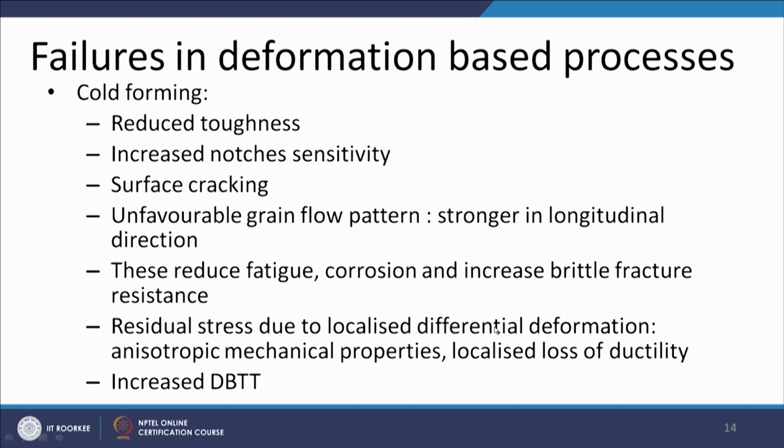Residual stress due to localized differential deformation, meaning more deformation at the surface and less in the core, and increased anisotropic mechanical properties and increased loss of ductility, all these increase the tendency for failure, especially in case of the cold deformation based processes.